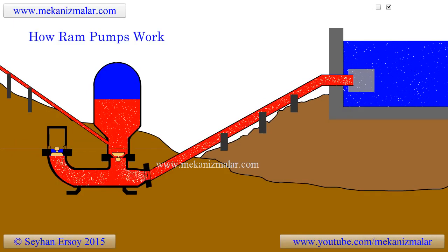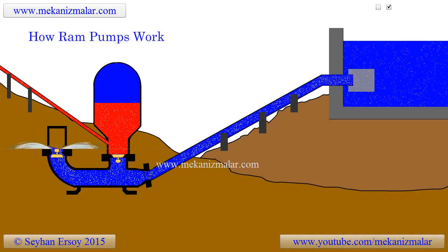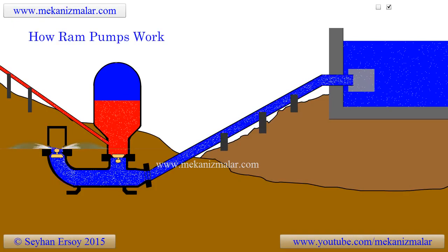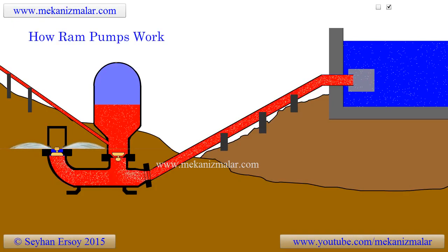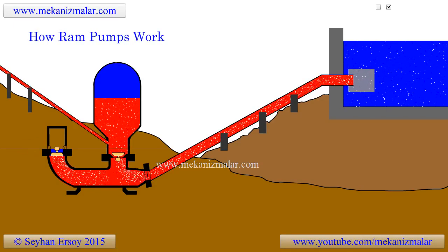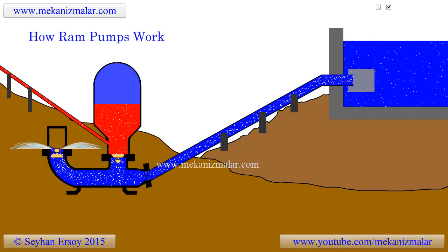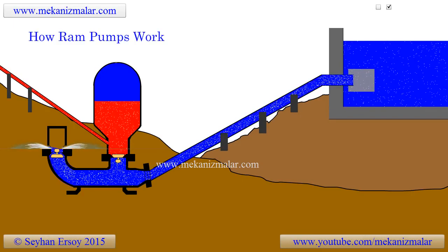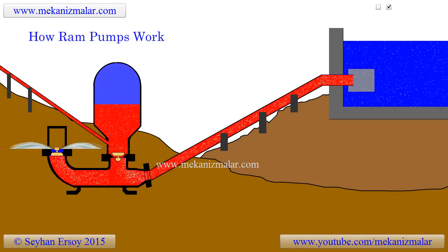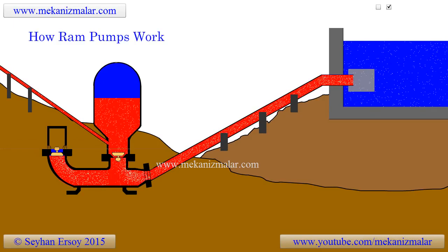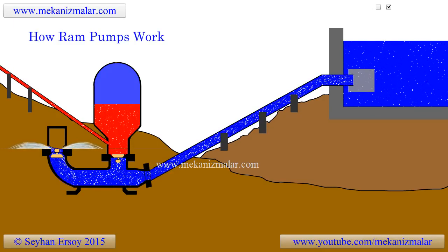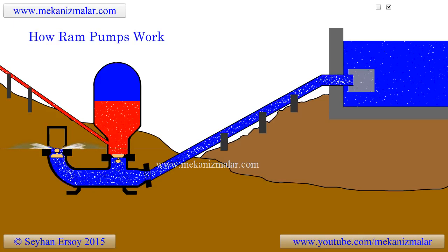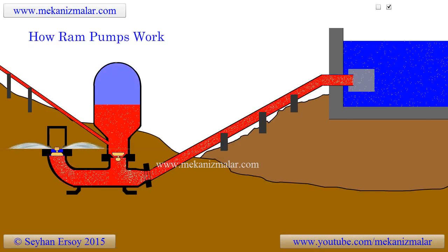The system may seem like it's disposing too much water, but it's not the inefficiency of the ram pump, but instead the requirement of the conservation of energy principle. If 10 liters of water per second is fed to the ram pump, and 2 liters of water per second would pump to 100 meters of elevation, this would violate the conservation of energy principle. But a quarter liter per second is a darn good flow rate for the system mentioned, and does not violate any energy principles.